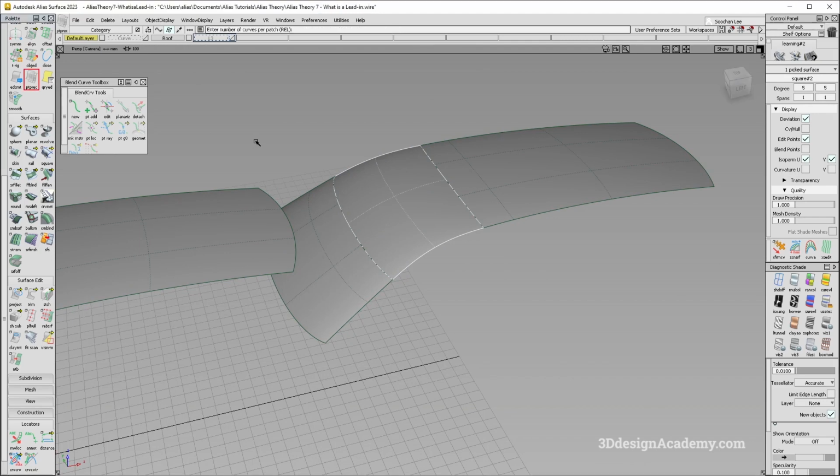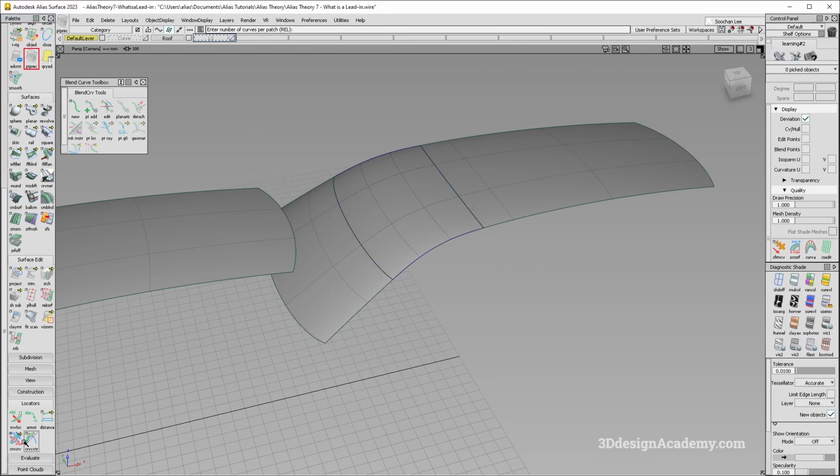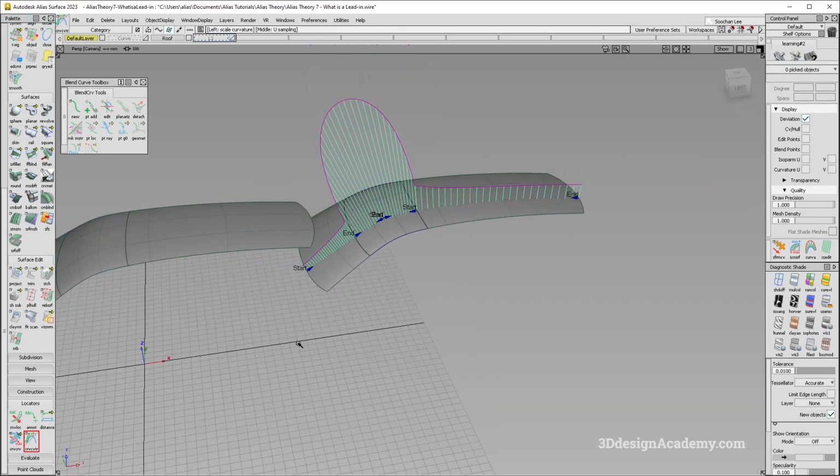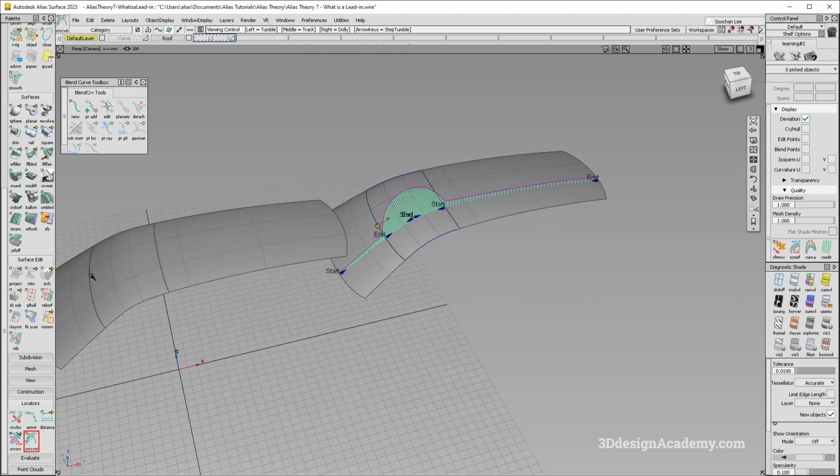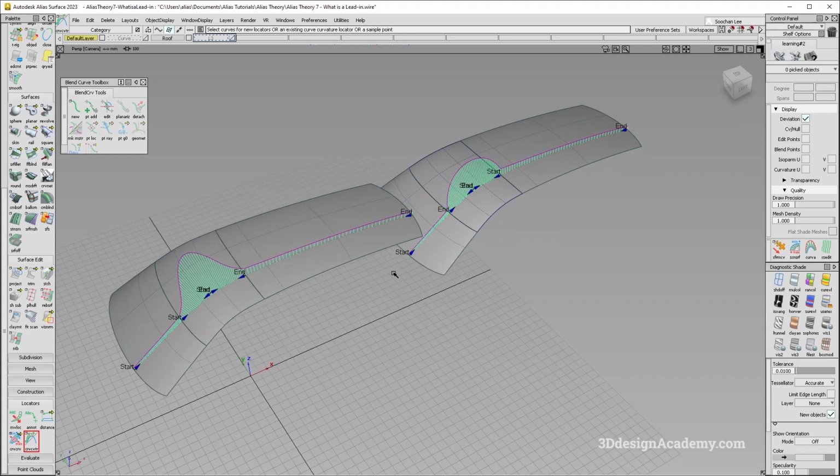I'm just going to turn the patch precision on like this. And let's just check the curvature. Now, you see that there's a little bit of acceleration on the primary surface, but the transition here is a little bit more abrupt, whereas this one is very nice and smooth.